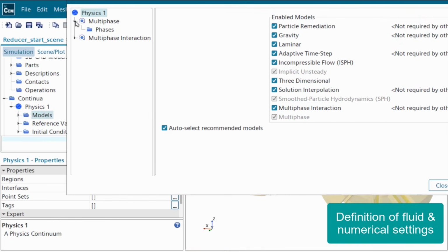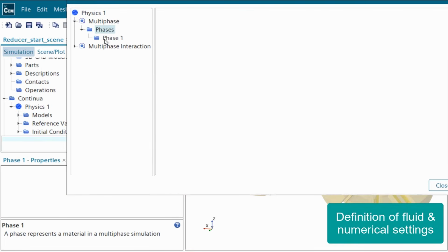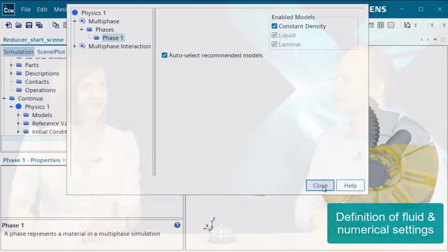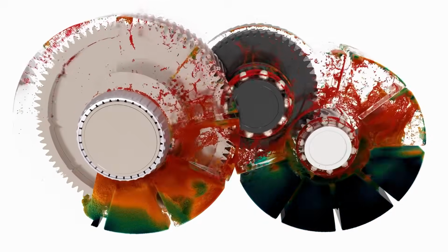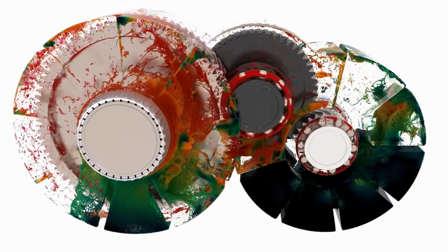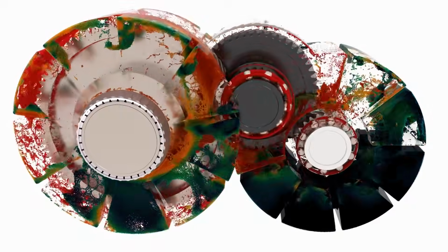Yes, we are seeing here in this video how easy it is to set up SPH in Simcenter STAR-CCM+ now. One question, what applications are we specifically targeting in this first instance of SPH? In this first version, we're targeting gearbox lubrication applications. Right. In terms of monitoring, we can monitor the churning losses, so look at the torque evolution, and we can of course also look at the evolution of the particles in the domain.